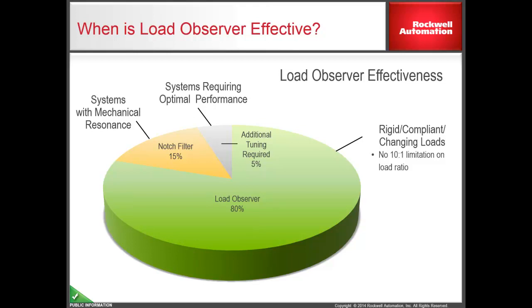Some applications exhibit a mechanical resonance which can be eliminated with a notch filter that is simple to configure. When used in conjunction with the notch filter, the Load Observer feature is effective for 95% of applications and eliminates the need to hire or train an expert. The remaining 5% of applications require additional tuning for peak performance. Let's take a look at several key benefits of the Load Observer feature in more detail.